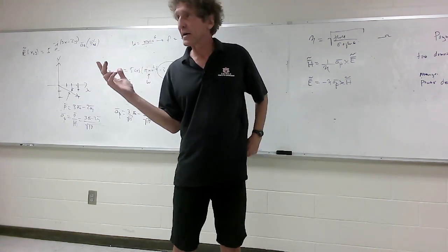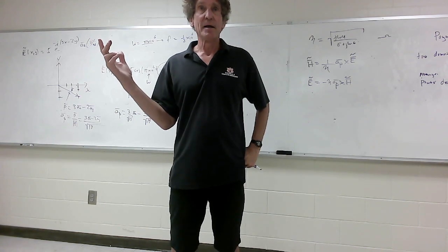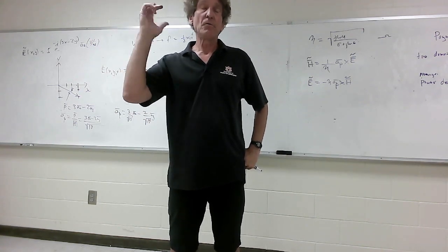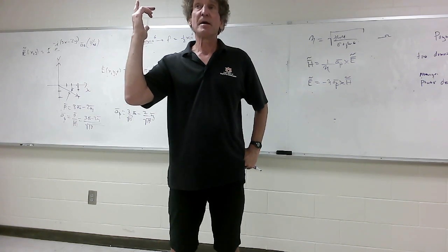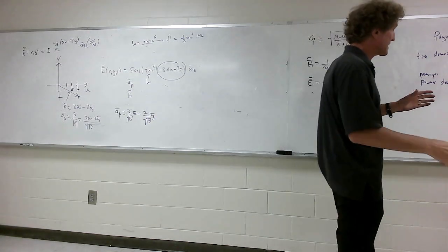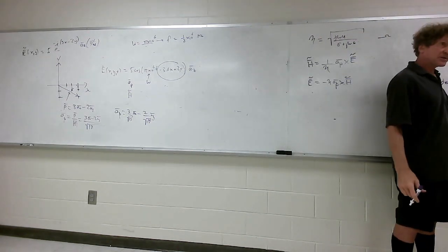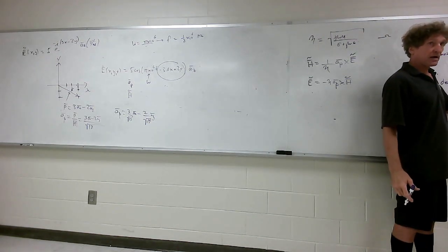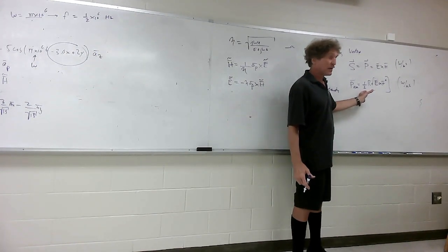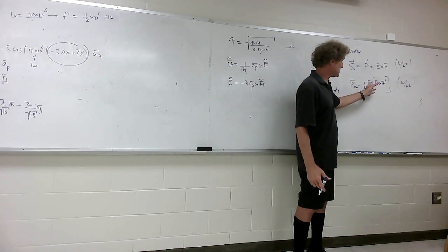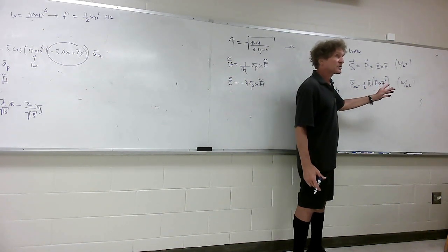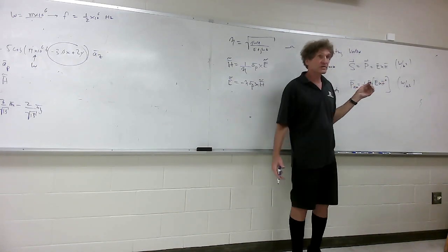Everybody has a right hand. I think I brought this up last time, didn't I? I hope. Anyway, if you want to know how to find the direction of propagation, E cross H is always the direction of propagation. Remember I said that this thing is going to be a magnitude and have a vector sense to it? The vector sense is the direction of propagation. The magnitude is going to be just the magnitude of E cross H conjugated. And the vector sense is going to be what's left of E cross H.